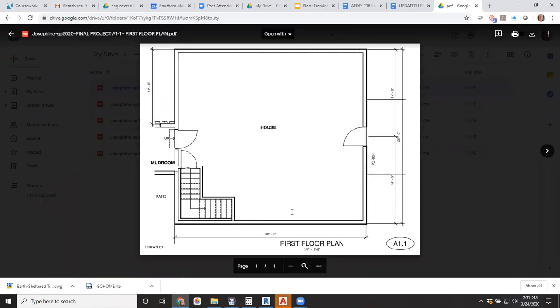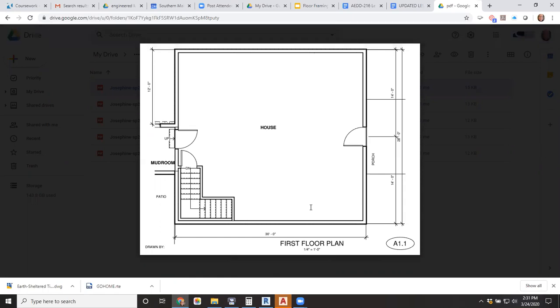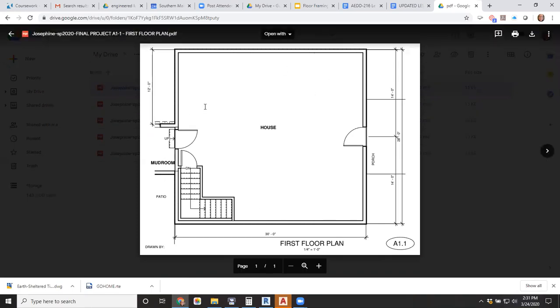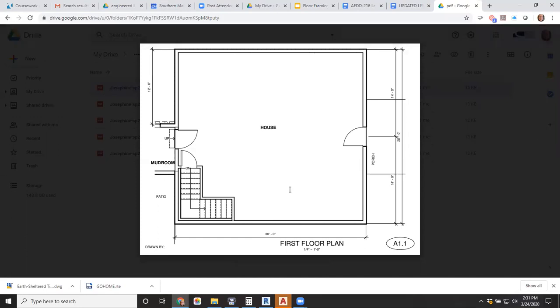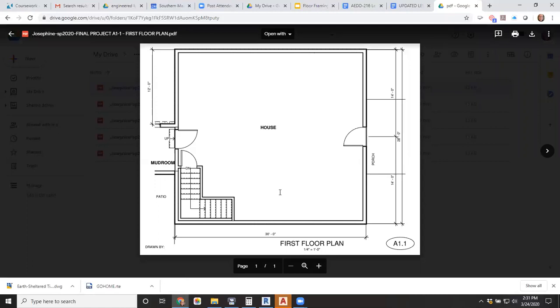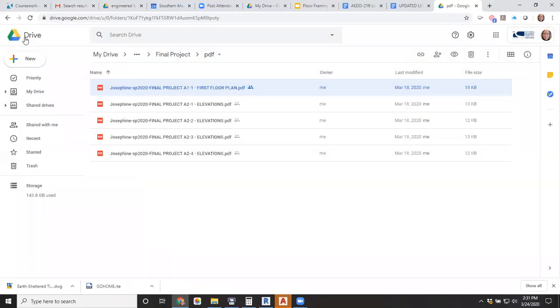If you print this at a scale of 1:1, making sure it's at a custom full 100% zoom, in other words, you're not scaling it to fit on your sheet, then when you print this out on your plotter or printer at home, it should print out at 1/4 inch equals a foot. So you could actually draw on this to scale and add your house layout here. And I have criteria. That's why I gave you the whole lesson plan for the rest of the semester ahead of time, so if you wanted to go ahead and do things, you can.